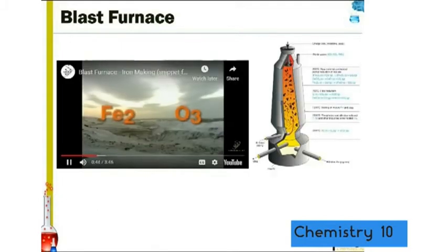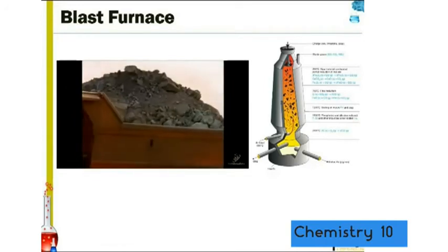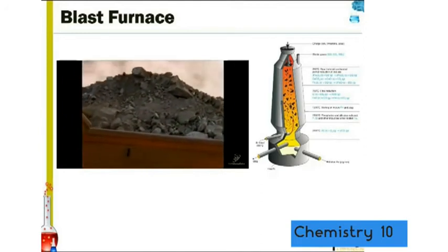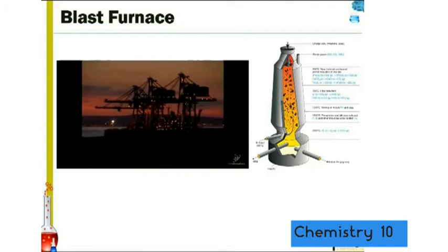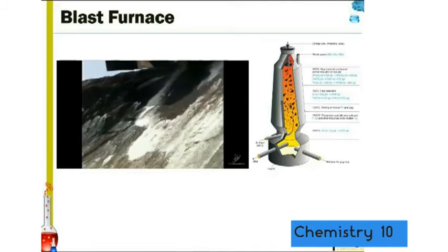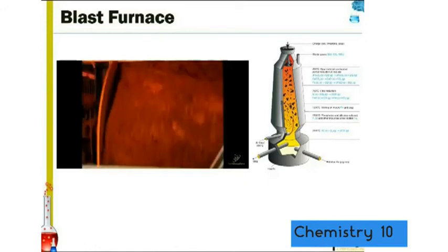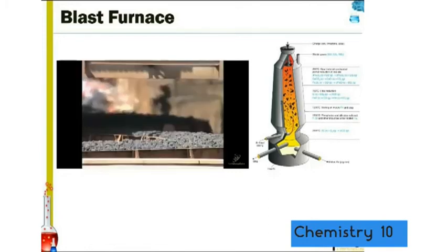Iron ore is common in the Earth's crust and contains iron chemically bonded to oxygen. This is mined in places such as the Americas, Australia, and Scandinavia, and then shipped around the world to steelworks. Ores are then blended together to produce a favourable mix. This mix is combined with coke and heated to produce the iron-rich material called sinter. Sintering reduces waste and provides an efficient raw material for the blast furnace.